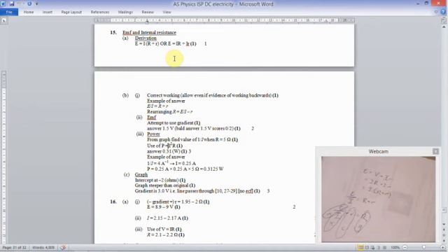It says 4 amps. It says over here, yeah. 1 over is 4 amps. So therefore this 0.25 is the actual current. So 0.25 squared multiplied by 5 would give you the power. So get your reading off the graph, do 1 over it, and then multiply that by the resistance. Excellent.